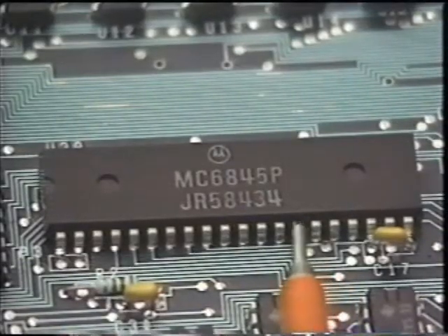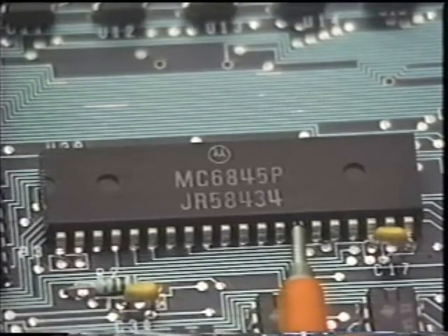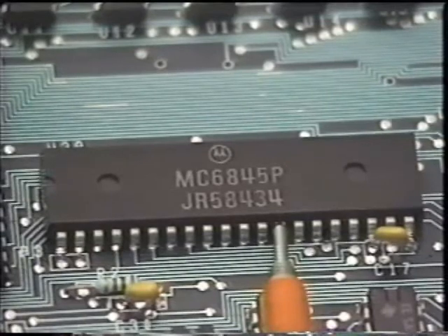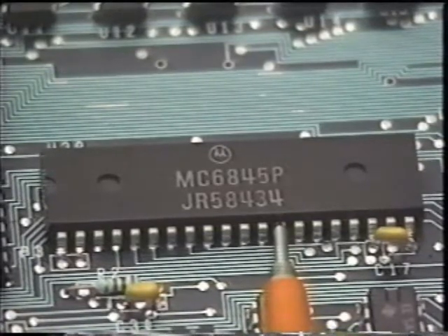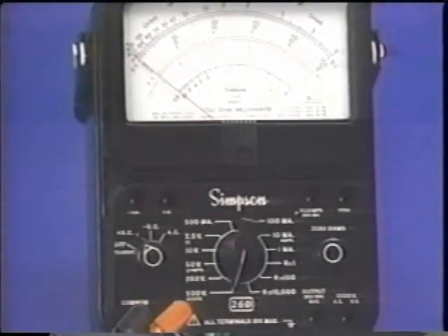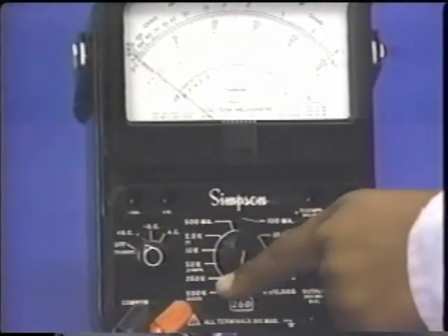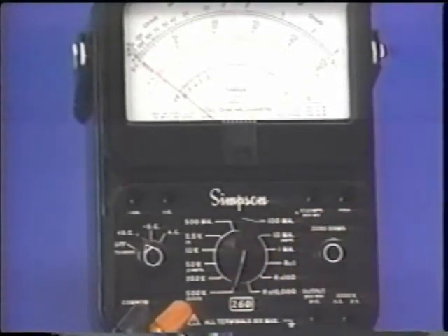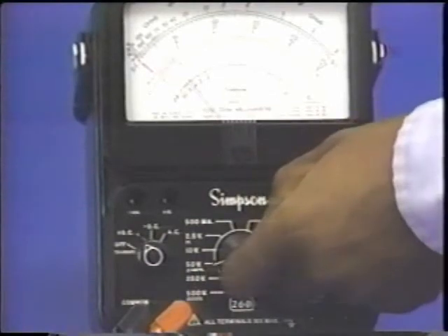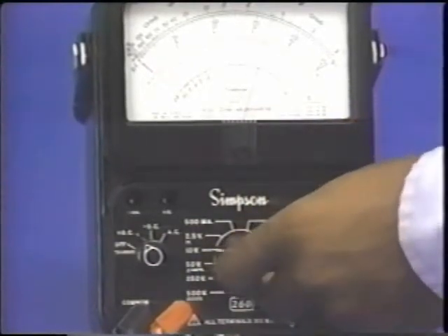When taking measurements, touch only one contact at a time. Touching more than one contact at the same time will often short out the circuit, causing damage to the components. If you are in doubt as to which range to select when doing voltage and current measurements, you can protect the multimeter by selecting the highest range. If the value being measured is within a lower range, continue to set the switch to the next lowest range until you find the one that provides the most accurate reading.